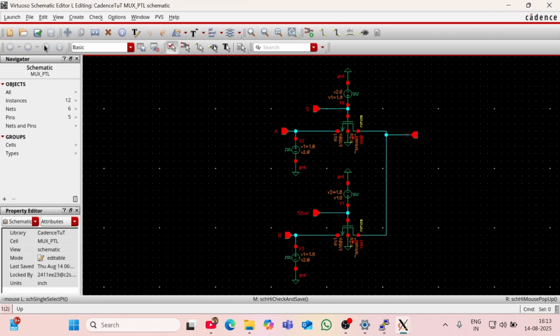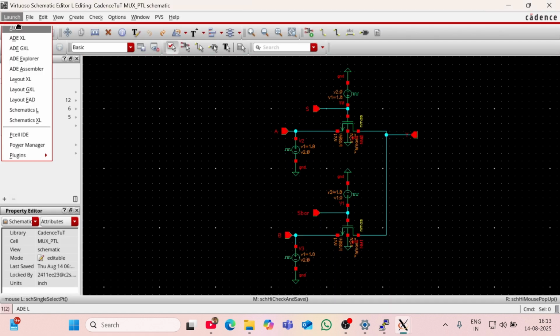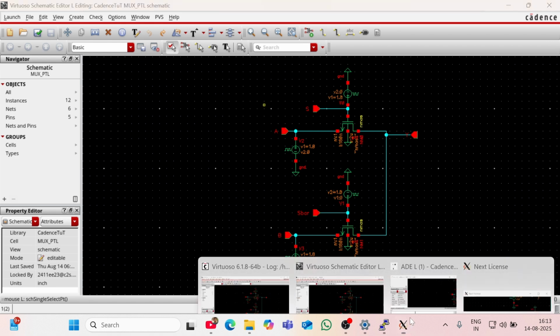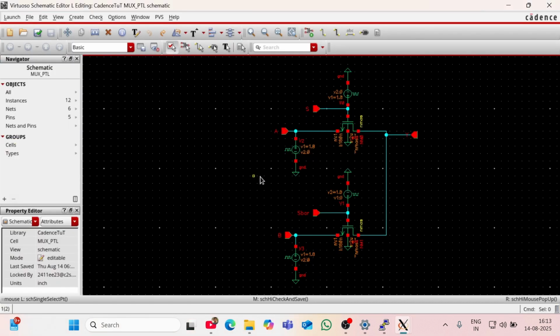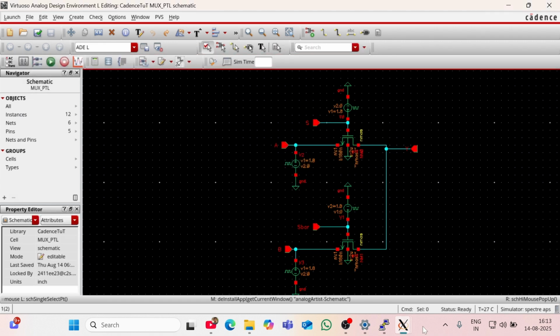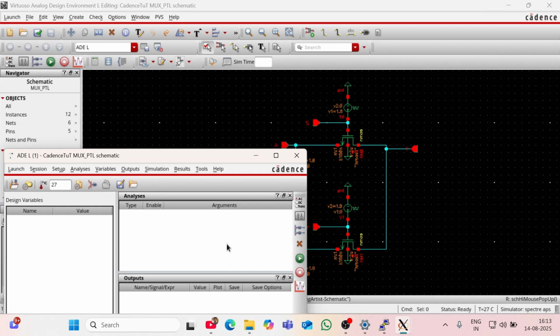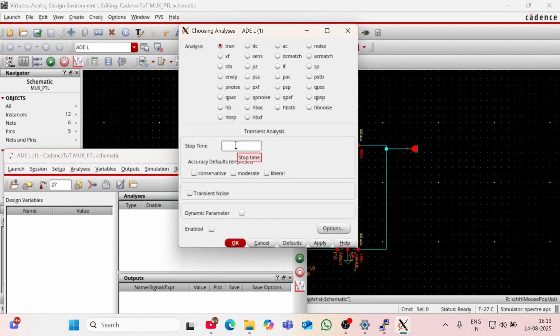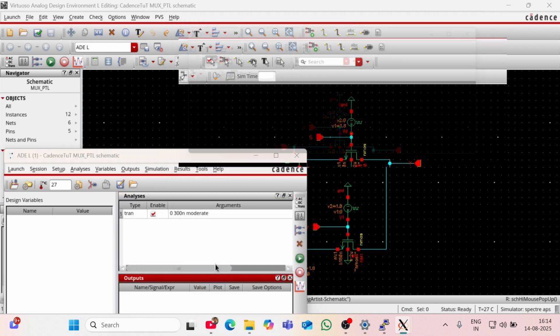Now again go to launch ADE, so go to session and then right click here, go to edit. I'm taking 300 nanosecond as the transient time this time, and okay, then edit.